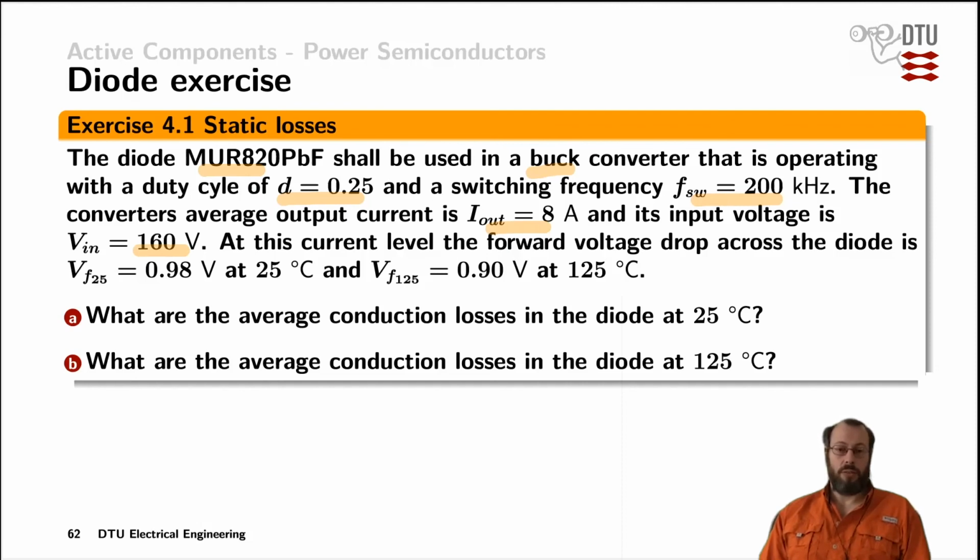In practice, for dimensioning power converters, this would rarely be the case, and you would need to interpolate the numbers or derive them from the SPICE model from a simulation to actually find out how the diode behaves at your specific operating point.